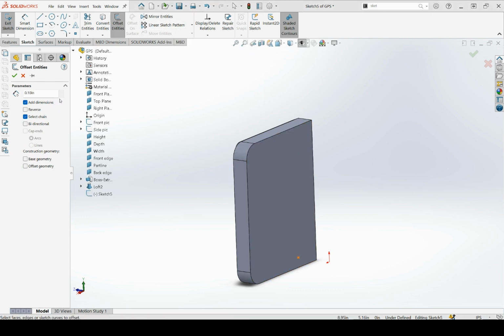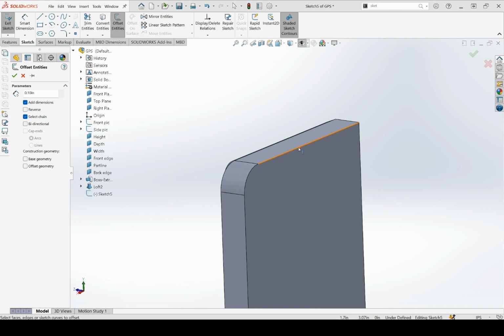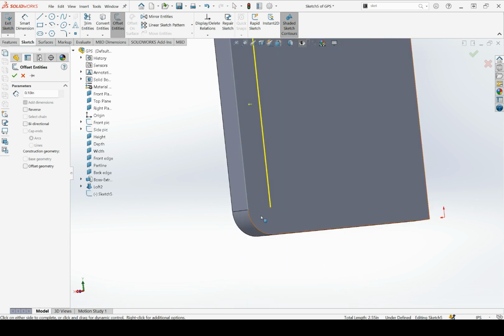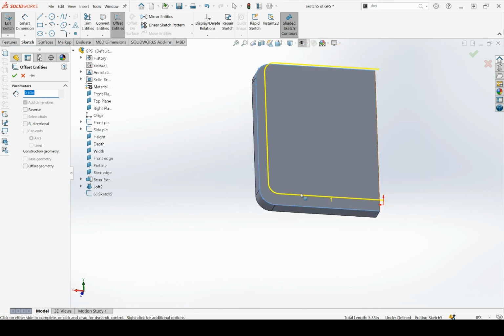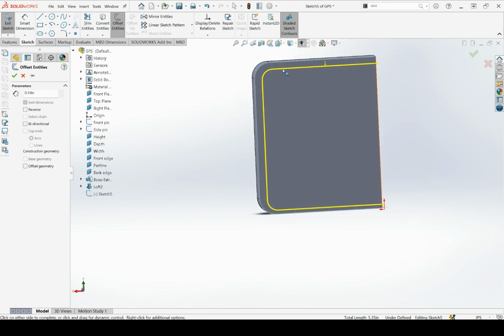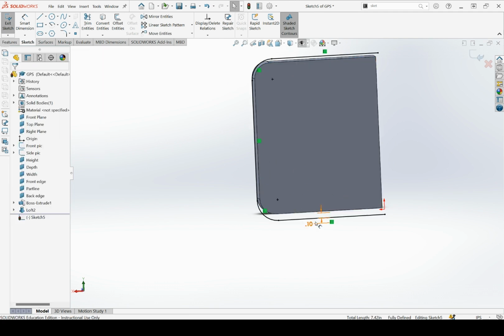To use this tool, I'm going to click on a continuous chain of edge pieces. You want it to be highlighting orange before you click. So this edge, click. This edge, the little part of the circle, this one. Then down here, I'm going to keep clicking when it's highlighted orange on the correct edge. And now I should have this preview of this yellow chain. If you make a mistake, oh, that wasn't what I wanted to do. Okay. I'm going to click Control Z. That might be the best thing to do if you make a mistake.